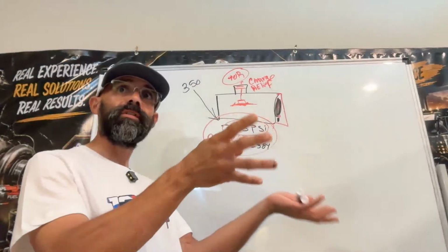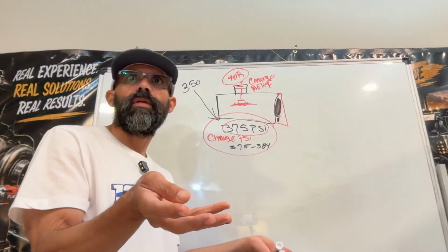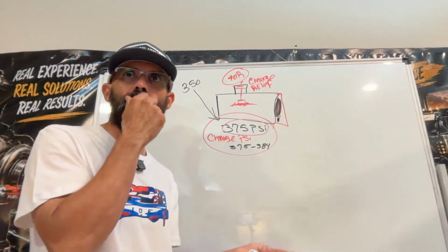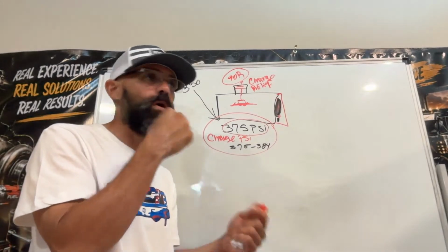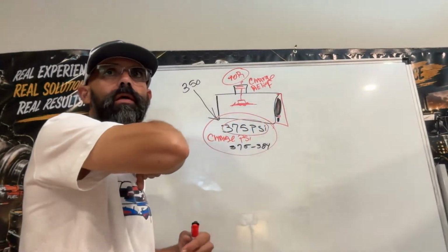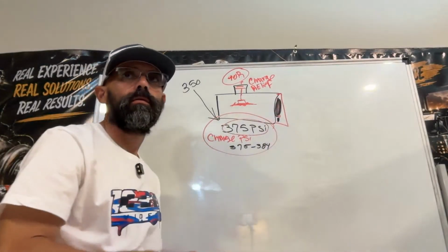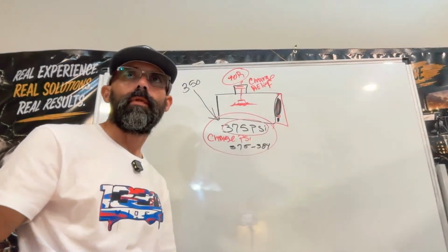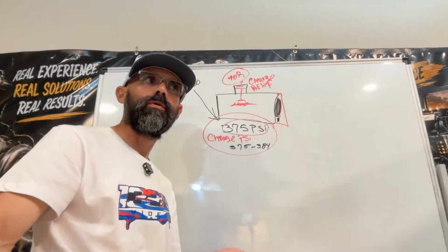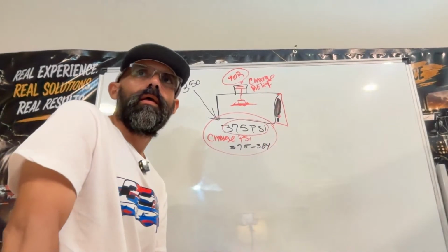As the engine wears down, the oil pump also wears out. And instead of 80 psi, now you're getting 50, right? So you've got to take into consideration, is it the relief valve, the cartridge? Is it the gears for the charge pump? You've got to also think about those components, I should say.